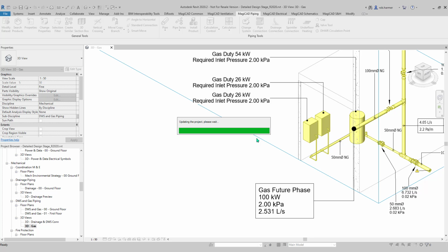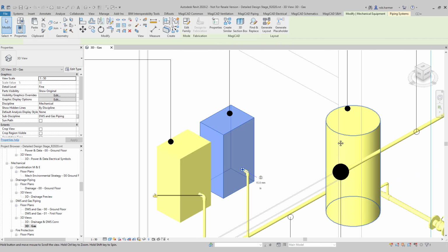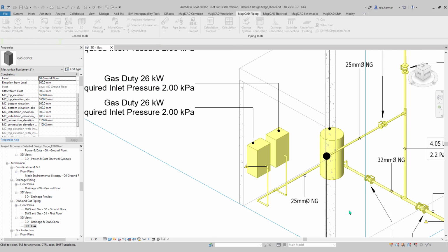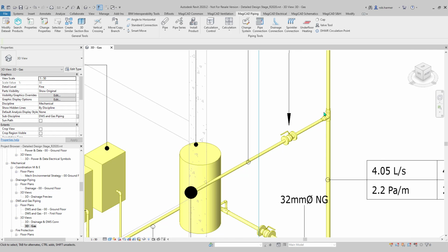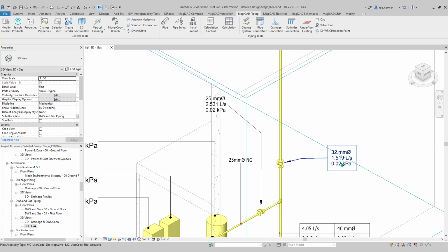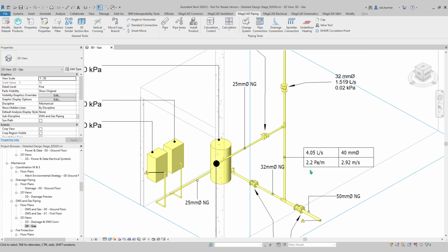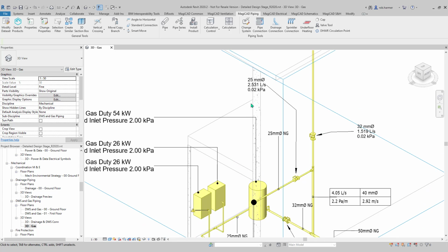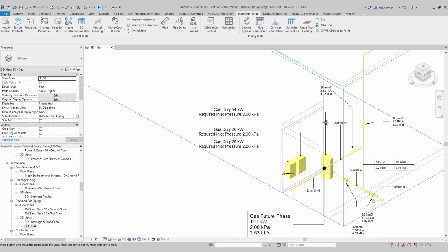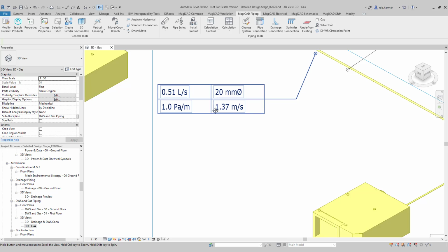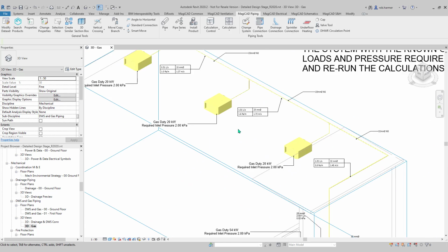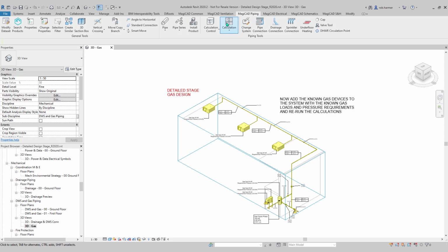Incidentally, I didn't continue the early stage design into this one, otherwise it would have been very, very similar to the pipework, but I wanted to show you the overall tool working with a beginning pipe size of like 100 mil or whatever it was, so you can see it all reducing. And you can see as well what it did to the valves. It also reduced the valves or resized the valves to the new size as well, rather than just putting reducers on it, which is great. And you can see all those pipe work tags populated, so you can see all the detail of all the flow rates and the diameters and pressure drop per meter, etc., through that pipe work section.